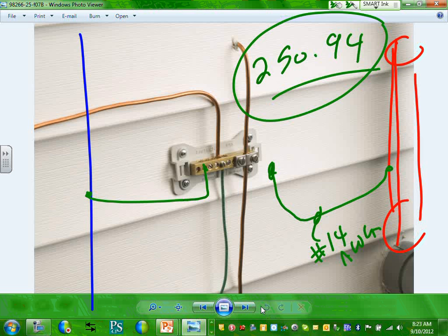Hopefully they'll do it. You have to do that, just install cable for like DirecTV or something like that? Yeah, yes, for new construction. But for existing, no. Existing is a different story. This has to be provided by the electrical contractor, so your building is already built. So for existing, here's what you're going to do. For coaxial cable, you drive a ground rod or you tie it directly to the existing ground rod.